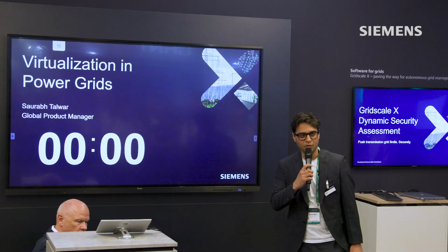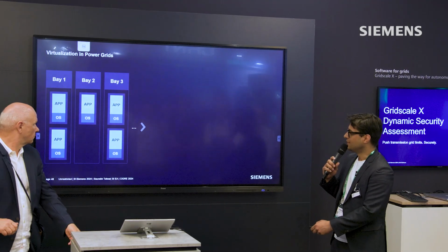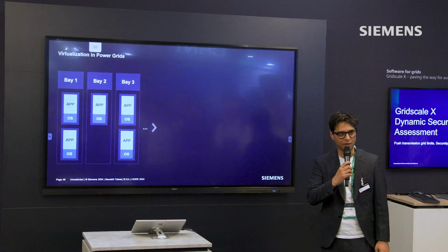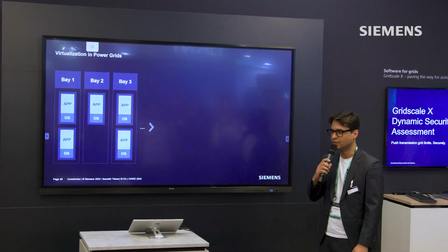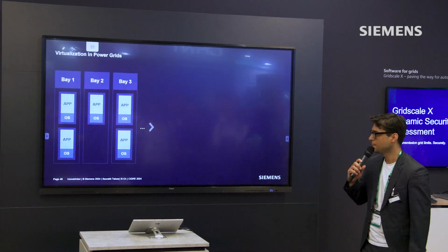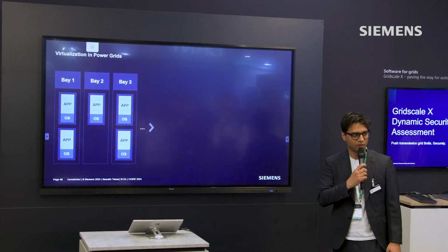So what is virtualization in the context of protection? Today, we do protection at a bay-wise approach, a feeder-wise approach, and each bay and feeder has a dedicated IED. The IED could be one or it could be more than one. Every IED has an application inside of it and also an operating system.